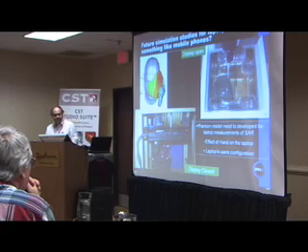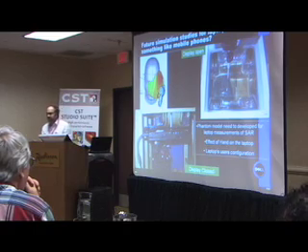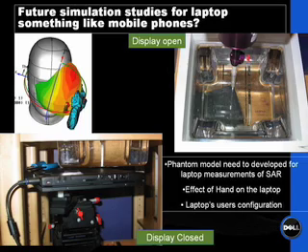And this is about the SAR. Initially SAR in laptops was not well known. It was more like a formality, and sometimes people were not even aware that the FCC requirement was a big deal. The reason is that the FCC requirement is that antennas should be 20 centimeters away from the user. As long as it is that, you are pretty well done. It is as simple as that.